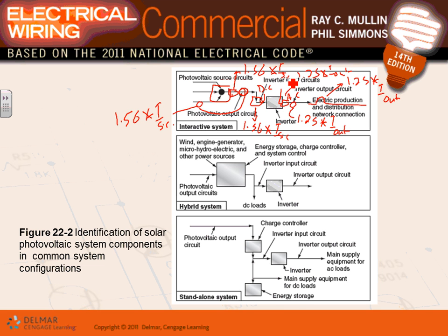So you have your solar coming in, utility interactive. You can see there is no storage. That's called the interactive system. That's what we talk about. There's something called hybrid, guys, where you can tie to the grid, and also you have DC. You can utilize it at DC load, and you also have another source of power here, generator or whatnot.